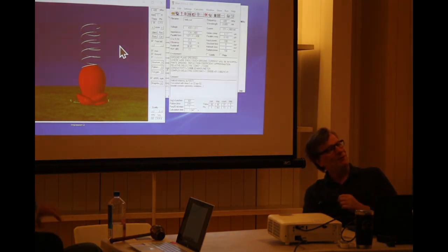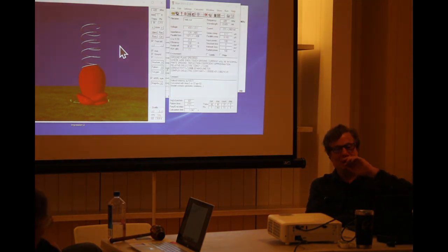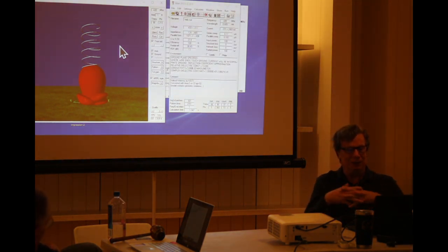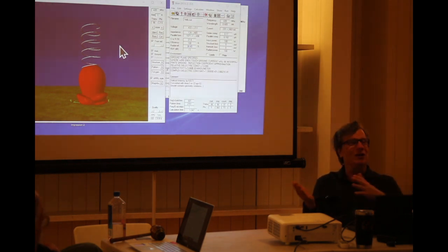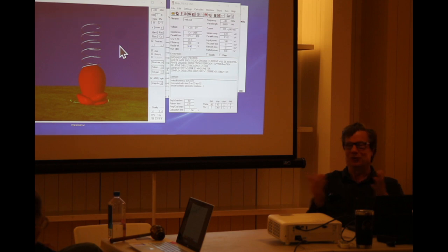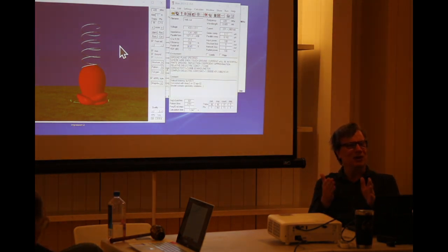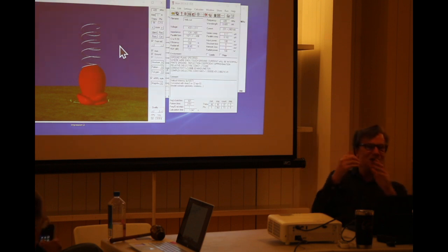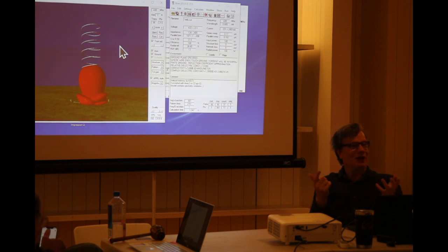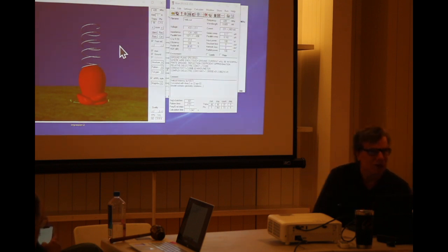But HARP does the same thing. When they were first building that, there was some hand wringing at the beginning. They were actually shutting down adjacent transmitters with the SWR trigger. So what do we do with that? Well, we could do what the military said, put a dummy load on it, but rather than do that, they put recirculators in each antenna and they feed that power back, not to the next antenna, but two antennas away from it. So now they don't dissipate that power, they simply feed it back where it's going to do some good. So very clever design.